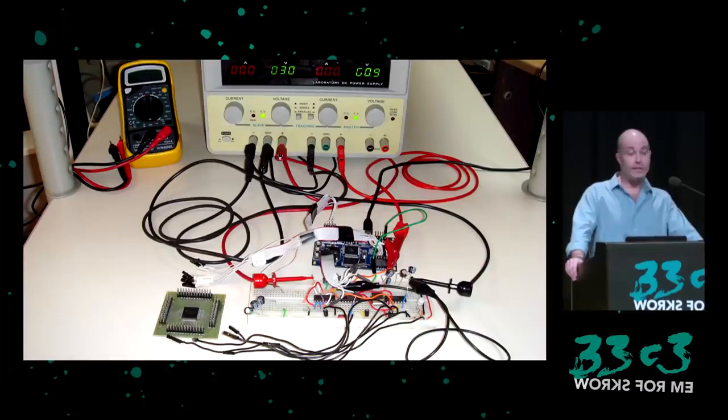Timing tests of the ACP suggest that the 6502 is running from an internal clock source, so this ruled out a clock glitch attack. A VCC glitch makes sense, and with the age of this chip, it seemed reasonable to expect that it would be susceptible to VCC glitches. The stronger protections against this type of attack are relatively recent.